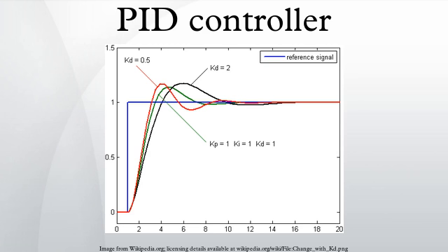Discrete implementation. The analysis for designing a digital implementation of a PID controller in a microcontroller or FPGA device requires the standard form of the PID controller to be discretized. Approximations for first-order derivatives are made by backward finite differences. The integral term is discretized, with a sampling time, as follows. The derivative term is approximated as. Thus, a velocity algorithm for implementation of the discretized PID controller in an MCU is obtained by differentiating, using the numerical definitions of the first and second derivative and solving for and finally obtaining the result.